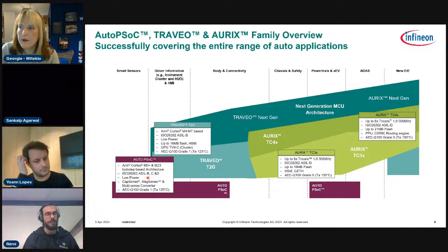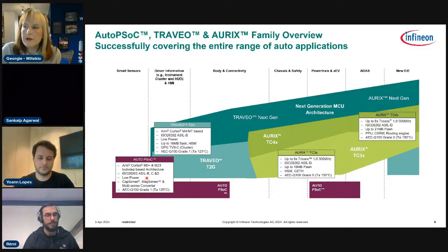As it is based on the Cortex-M architecture, it supports different low power modes. And as I mentioned, it is very rich in features related to the analog front ends. Other than that, it has CapSense integrated, which is the 5th generation of CapSense with very good signal to noise ratio.